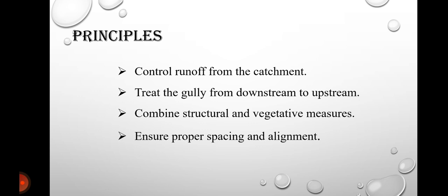It traps the sediment. Structures should allow soil particles carried by runoff to settle and accumulate. It stabilizes the gully bed and the banks, which should be protected from further damage. Safely dispose of excess water. Structures must provide a safe passage for overflow water without causing damage. Increase infiltration. Slowing runoff gives more time for water to infiltrate into the soil.